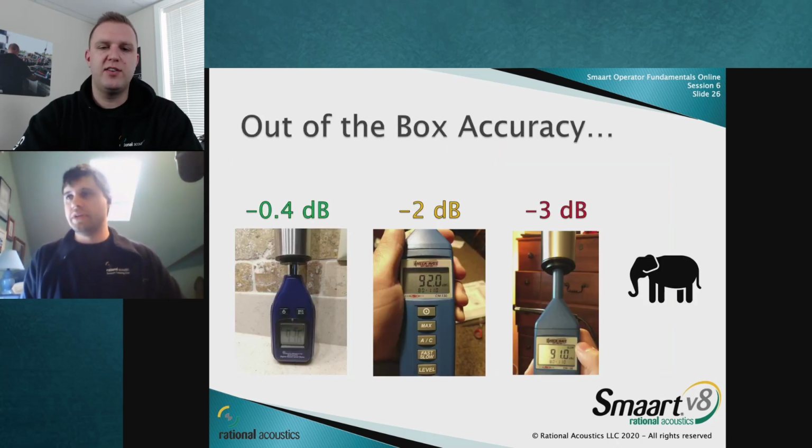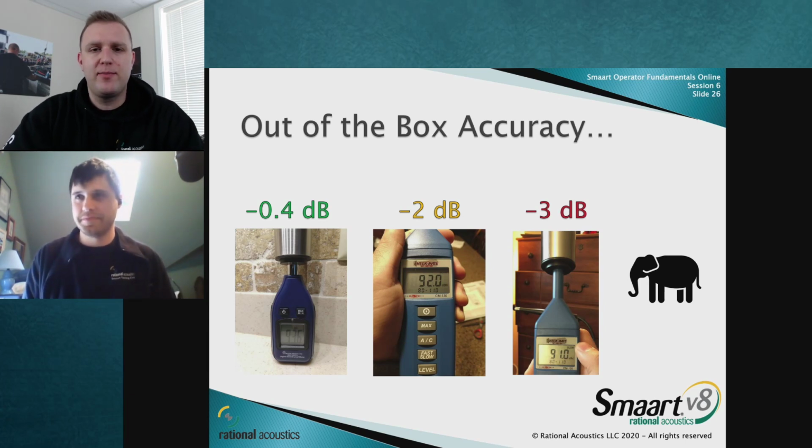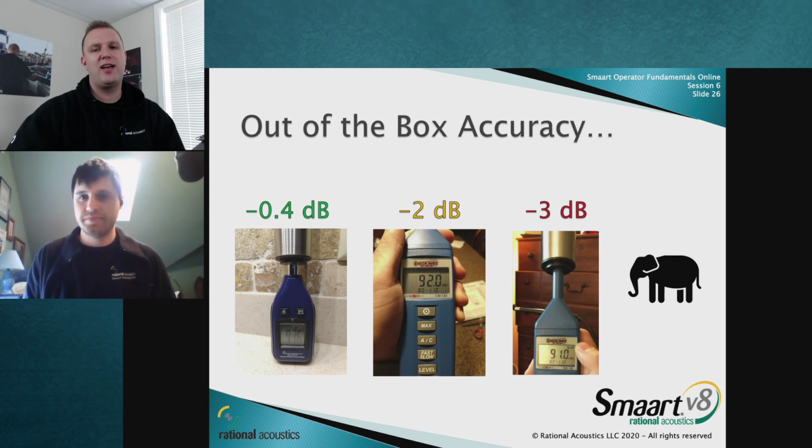Yeah, and just to touch on how do you know your calibrator is accurate? Well, when was the last time you changed the batteries? Good point. Because we're talking about an electronic device, and I know the iSemcon calibrator takes a 9-volt battery. If you don't change the batteries in that for a year or whatever, and you start to measure, expect it to not be accurate. Right.